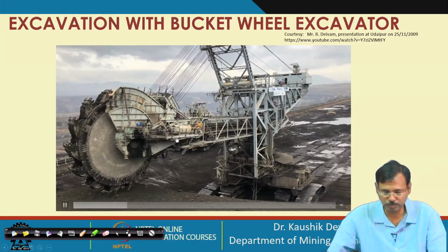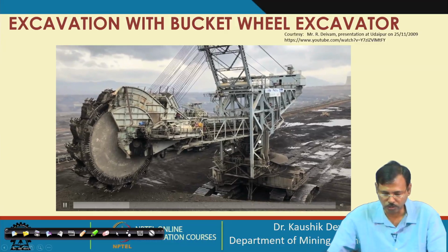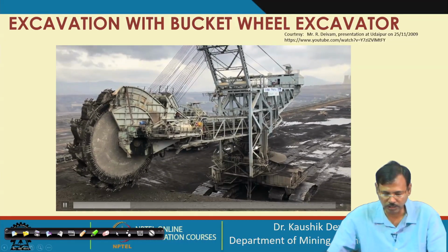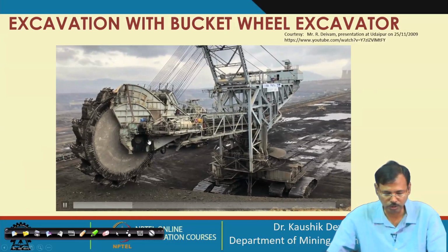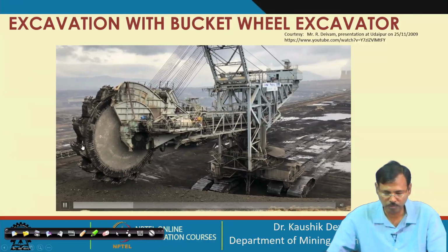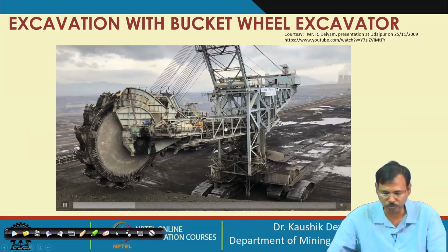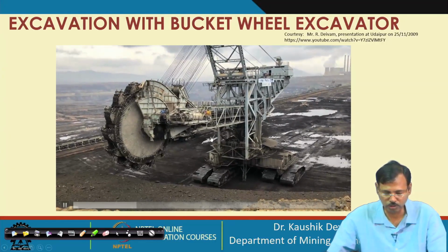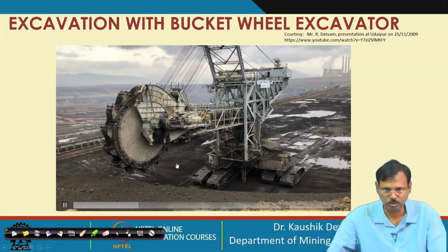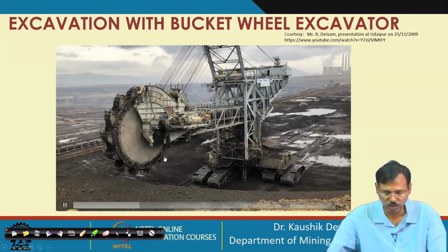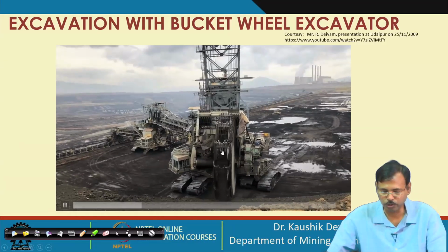And you can see this boom is slewable, telescopic type, it can move, it can rotate. So, it can rotate in 360-degree direction. In telescopic formation you can extend the arm, you can reduce the arm length, and that is why this can negotiate. Now, it is moved with the reduced arm size, and it can be raised or it can be lowered. So, that is why it is able to serve a very high bench height also.